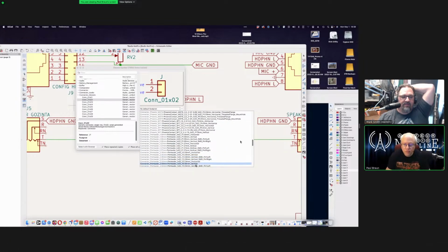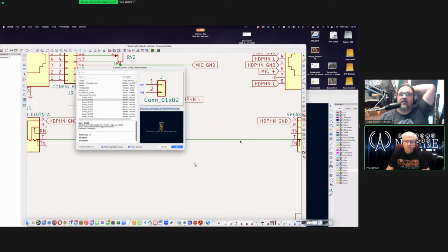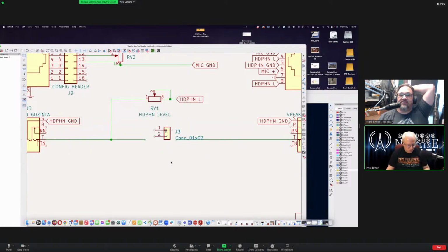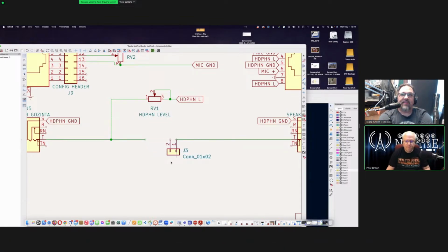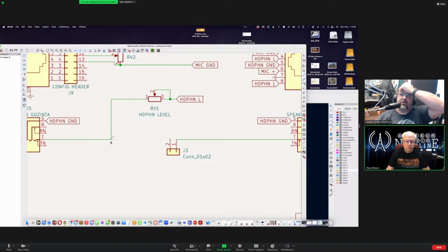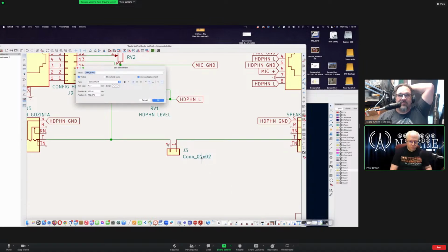2.54. Hey, Brian. 2.54 vertical, right? That looks right to me. Yep, that's the correct one. So now the fact that your schematic is labeled 1 and 2 and your board footprint is labeled 1 and 2, that's the important part. So what it was complaining about before is that your schematic nodes connected to pins A1 and B1, but when you went over to import that into the board layout, it didn't have an A1 and B1 with nodes connected to it.